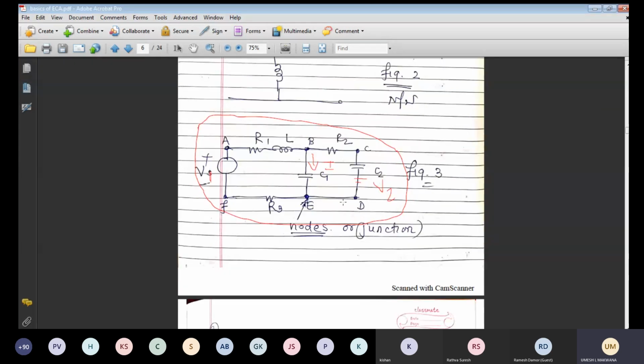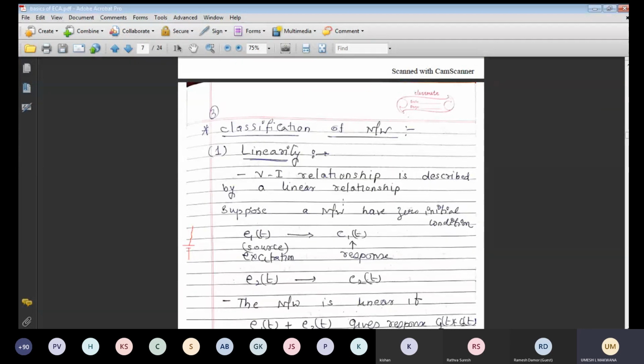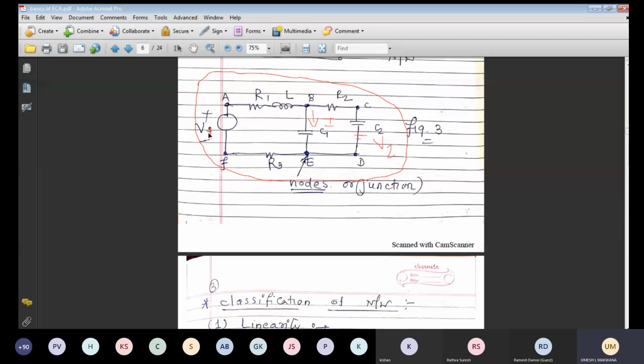Now the basic concept is, when we apply the first voltage V1, by keeping the other voltage short circuited, we remove that voltage and find the current in this branch. That current is known as I1 dash, because of only the V1 voltage.